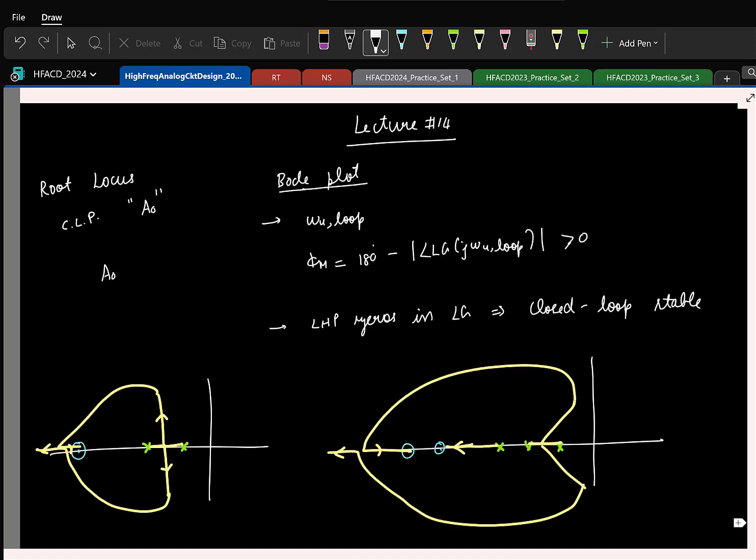So in particular, we will try to understand 2 things intuitively. That is, if we add a lot of poles in the system, why the system in closed loop becomes unstable. Secondly, how this act of introducing LHP zeros is improving the stability. So these 2 are 2 broad questions we will try to qualitatively find answer to in time domain, right? And for that, let's actually look at what happens when you have poles. So I'll take a simple first order system. Let us say we have something like this,